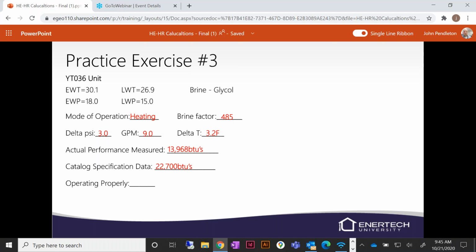So when I think about it, when you're in first stage, the compressor runs at 2/3 capacity. So it could just be that for some reason you're not in second stage. When we run first stage, second stage, it doesn't cut it in half. We run 2/3 capacity first stage, and then the other third kicks in for second stage. So in this example, first thing I would check is make sure it's in Y2. Make sure the compressor has a second stage call for it.